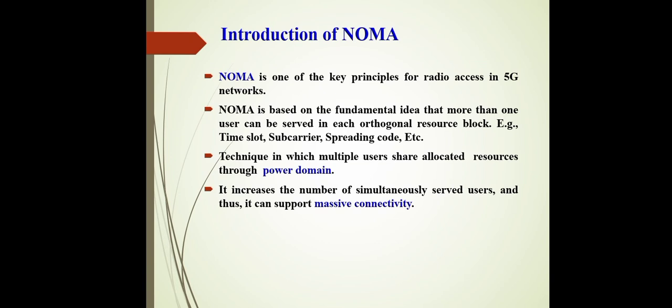NOMA is based on the fundamental idea that more than one user can be served in each orthogonal resource block, that is time slot, subcarrier, spreading code, etc. NOMA is a technique in which multiple users share allocated resources through the power domain. It increases the number of simultaneously served users and thus it can support massive connectivity.